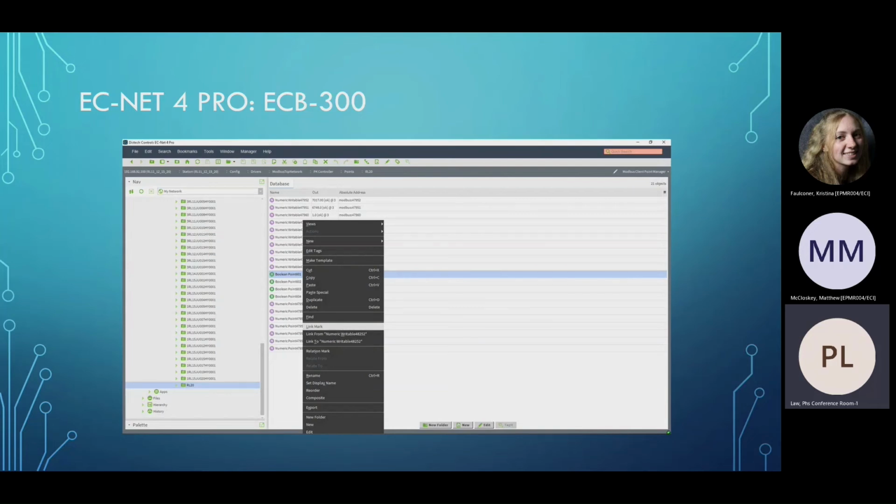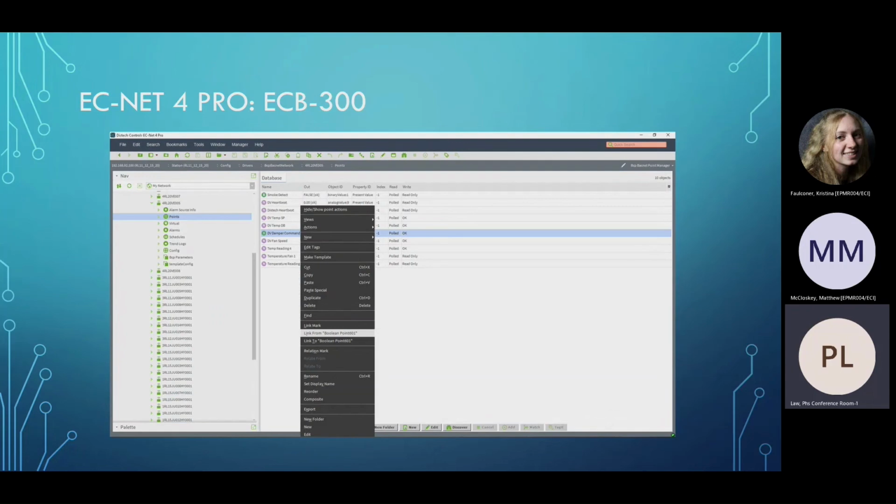The way you do that is, let's say this Boolean point 601 translates to the damper command for the 4RL20 BE5. So we right click on it, we say link mark, and we are in the modbus TCP network PK controller points RL20. And then we go back to the bacnet driver 4RL20 BE5 points folder, db damper command, link from Boolean point 601.